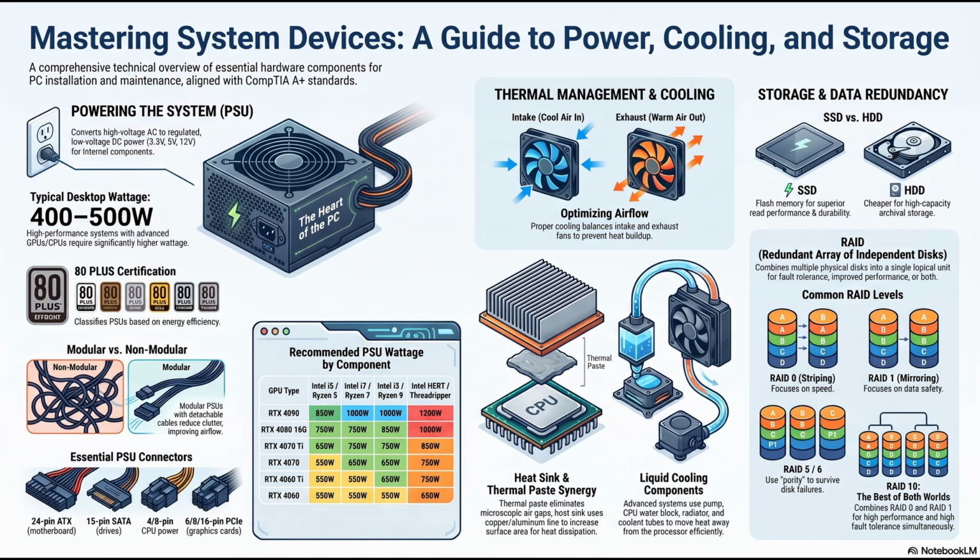Don't do it. Standard household vacuums rely on friction between the dust particles and the plastic hosing, which generates massive static electrical charges at the nozzle. If you touch a highly charged plastic vacuum nozzle to a microchip on your motherboard, it will discharge a localized lightning bolt, instantly frying the delicate logic gates. Always use canned compressed air or specialized anti-static electronics vacuums.